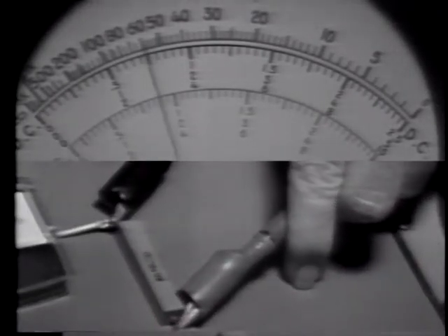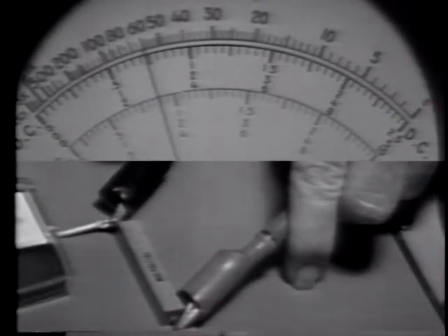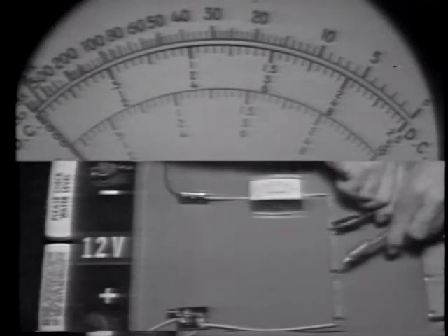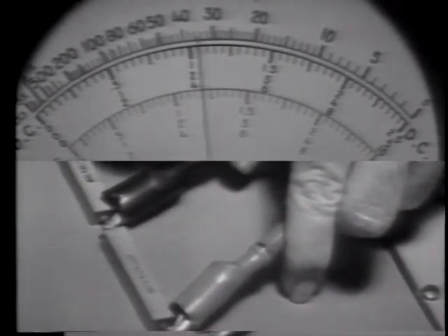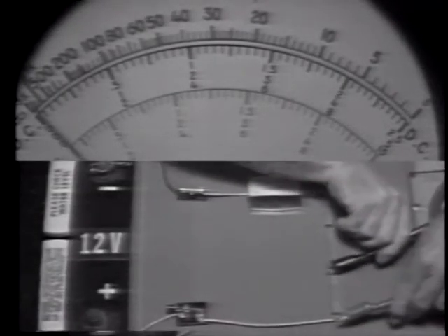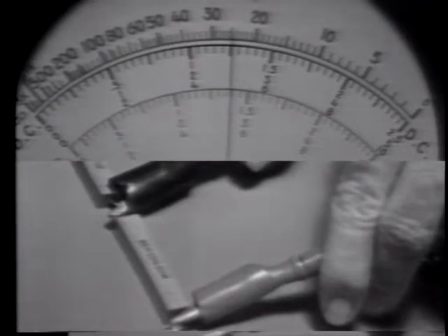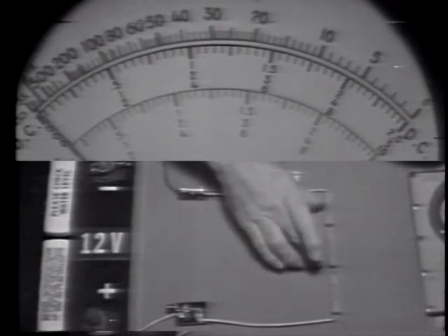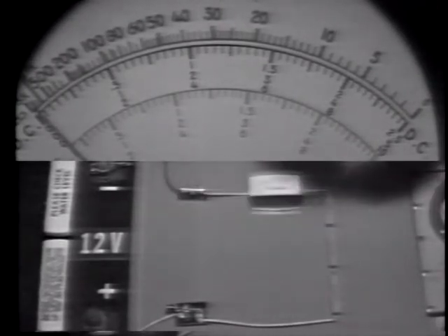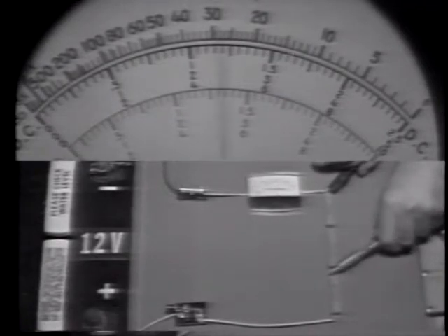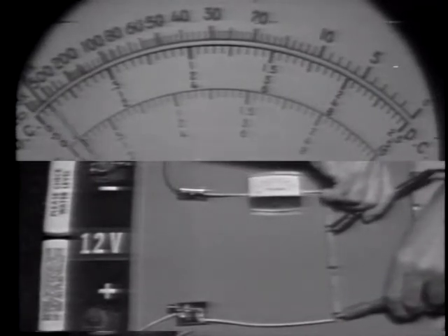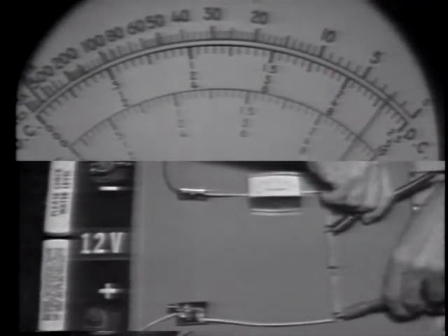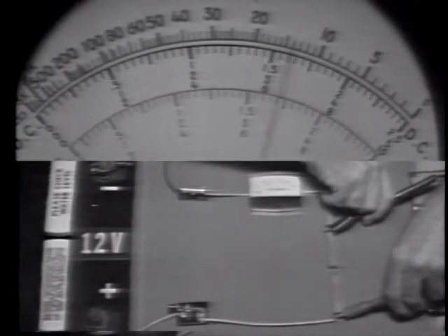And when using a voltmeter, remember, we must observe polarity. So across this one, let's call that 3 volts. Moving down to this one, let's call that one 4 volts. And this one, that's 5 volts. Now, of course, we can also obtain voltage from combinations of resistors. For example, if I measure across these two, we get about 7 volts. And across these two, it's a little bit over 9 volts, but we could call it 9 volts.